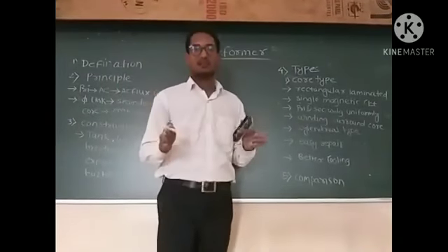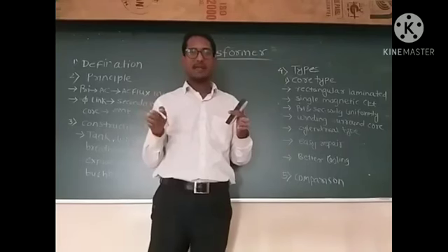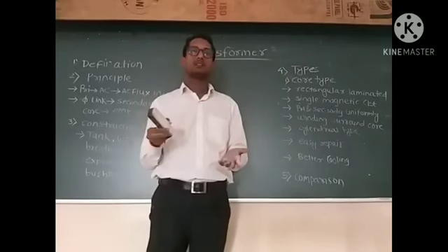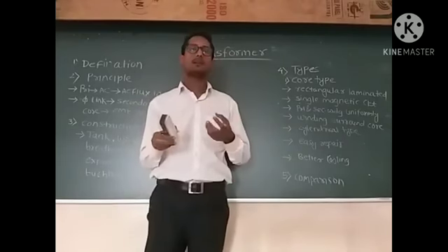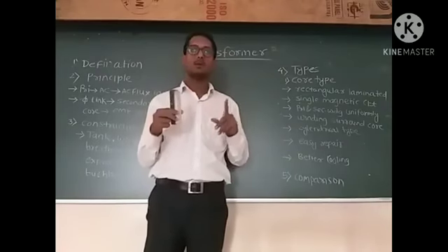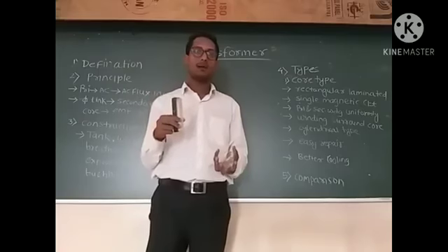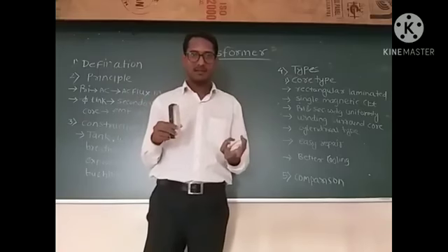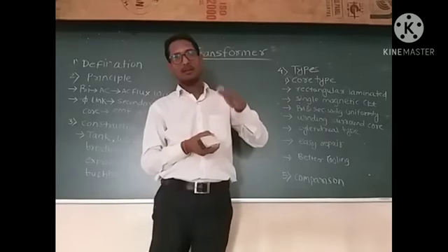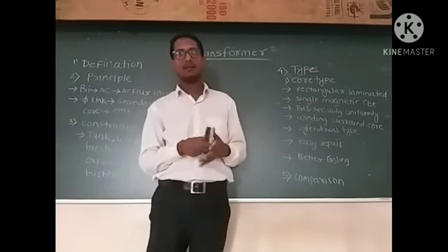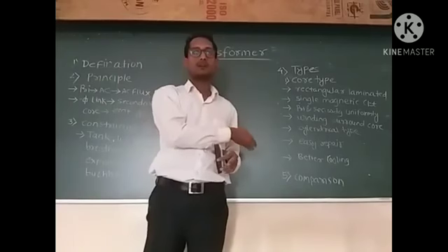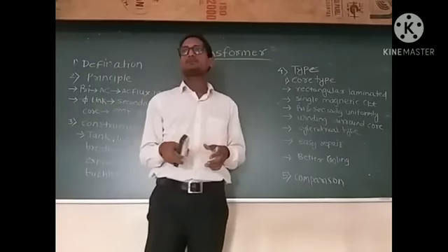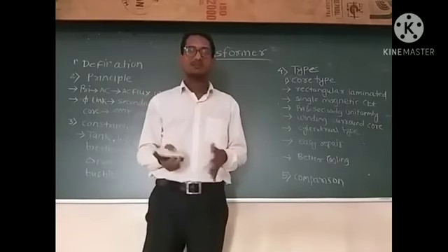Conservator is the external device of the transformer tank where all the transformer oil is reserved. At the time of contraction, when the transformer oil level decreases, the conservator gives oil to the transformer tank, and at the time of expansion, when the oil level inside the transformer tank increases,